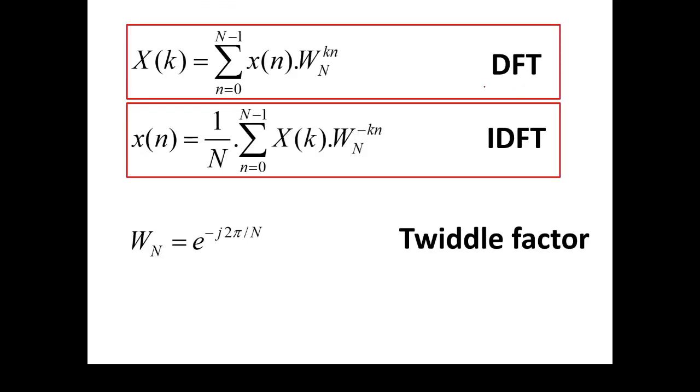So if you look into these equations, DFT and IDFT, both of them are now discretized. Herein, there is one component W_N^{kn}, regarded as the Twiddle factor, given by W_N equals e to the power minus j 2 pi divided by N, and for kn, it becomes this one multiplied by k, which goes in the numerator.